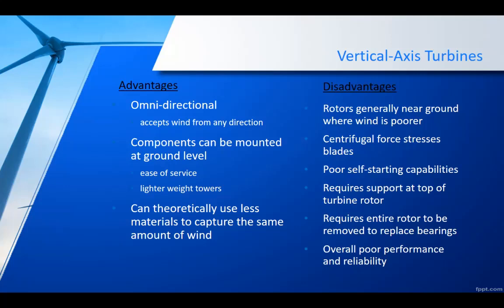So what are the disadvantages? In most cases, the rotors are near the ground and you have a lot less wind. Okay? The blades get a lot more stress from the centrifugal force, the forces pulling out because of the rotation. And so maintenance costs may be a little higher. They don't self-start well.